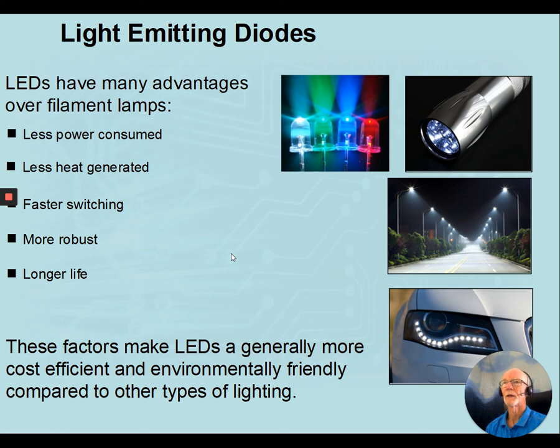So in the circuits that we're going to be using on this course, we're just going to be using the little indicator lamps, and in every circuit that we put them into, we have to be aware of the current limiting resistor required for the LEDs.